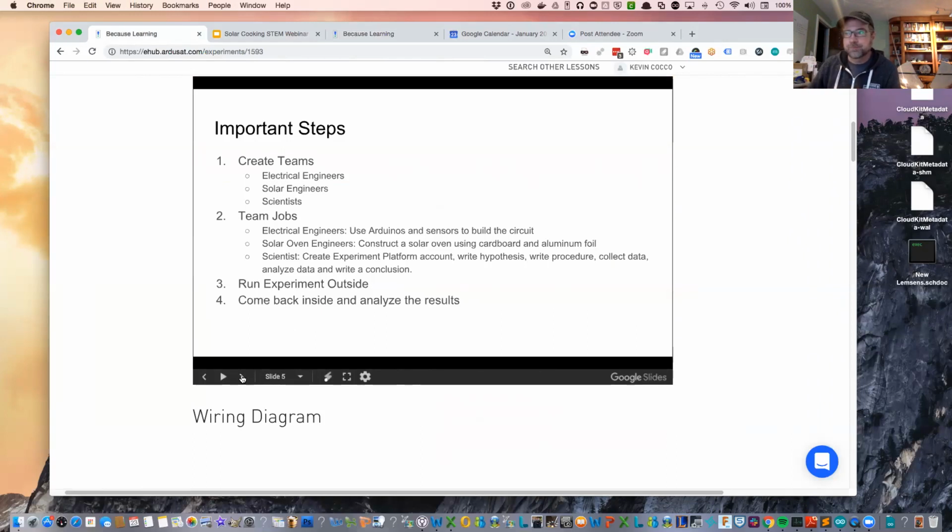Great. We have another question from Darren. Is there a temperature that we need to be careful of that may cause damage to the board or the sensor or the OLED? Good question. You should be good up to about 180 degrees. I would recommend you don't go over 140 degrees, and maybe keep your threshold for your alarm at maybe 120 is probably good guidance. But you'll have a pretty hard time with a pizza-type solar oven. I'm sure you guys do some good engineering, but we haven't seen anybody destroy anything with these yet.